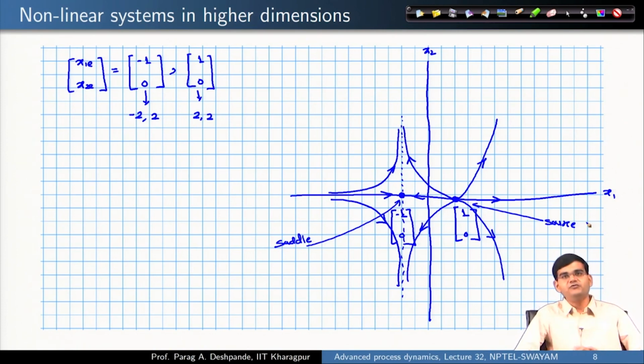So, this is how we will handle higher order nonlinear dynamics. The first thing you establish is the equilibrium solutions. The equilibrium solutions are arrived at by setting the individual equations to 0. Now, in most cases, since it is not possible to use the nonlinear model directly, you would like to linearize the system.